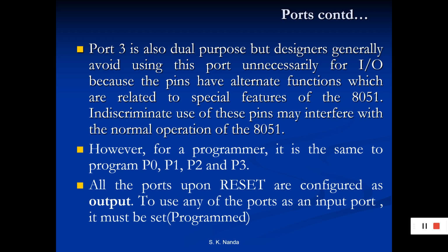However, for a programmer, it is the same to program port 0, port 1, port 2, port 3, everyone. All the ports upon reset are configured as output. To use any of the port as input port, it must be set to be programmed.